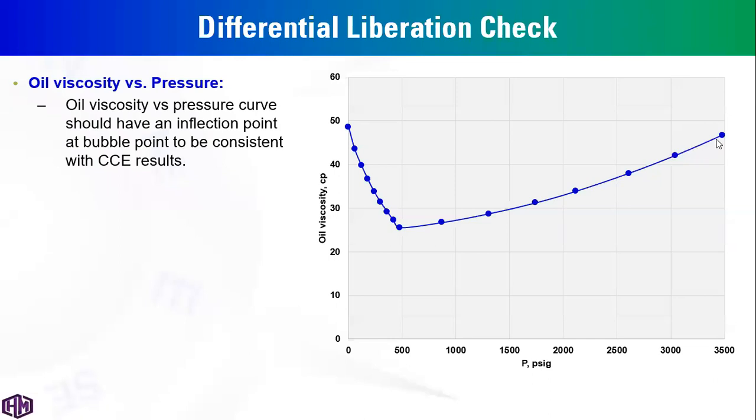So oil viscosity and oil density decrease with pressure decrease, but lower than the bubble point pressure, the density or viscosity will similarly start to increase, because the solution gas is released out of the liquid, which means the liquid becomes more viscous and denser due to the release of solution gas.